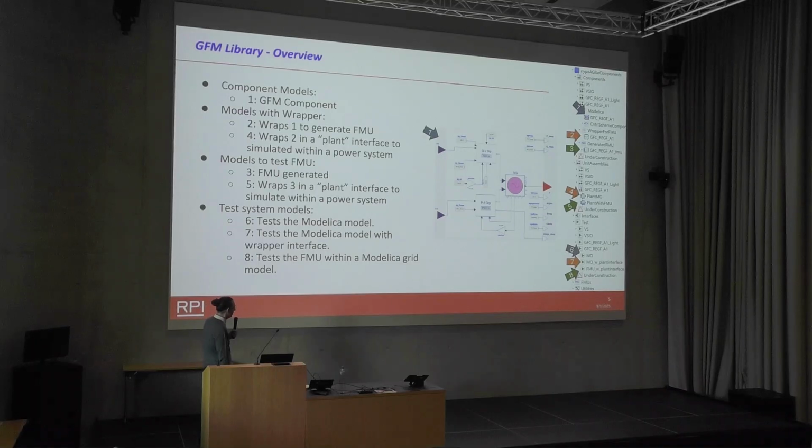This model is built based on industry standardized descriptions, which is basically a PDF with a bunch of block diagrams, so you gotta figure out how to implement that. So you see here at the top in that library that I made for them, there is the component right there. That component, of course, is built in object-oriented fashion. And then I have to generate an FMU for that simulator. So you have here a wrapper that I created. And this wrapper needs a bunch of things so that the FMU can be read by that simulator, because they're doing some weird things.